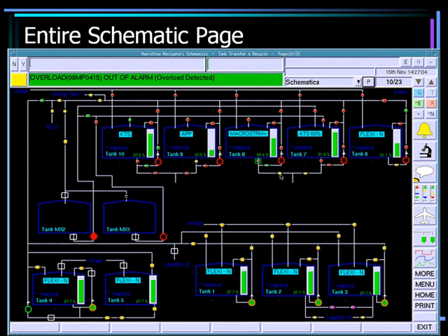So, Brian, with the tank map file, does the PLC actually, in the file, is there an attribute or an element that tells the PLC what the actual fluid is that's in the tank? No, only by number. The PLC's got a number associated with a product. Yeah. So it says the contents of the tank is 27, and when you're setting up a transfer to another tank, it checks that the destination contents number is 27 before it lets you. So what is it, MacroView or the PLC, that decides which tank element can mix with another tank element? You can't. There's no mixing of any products.